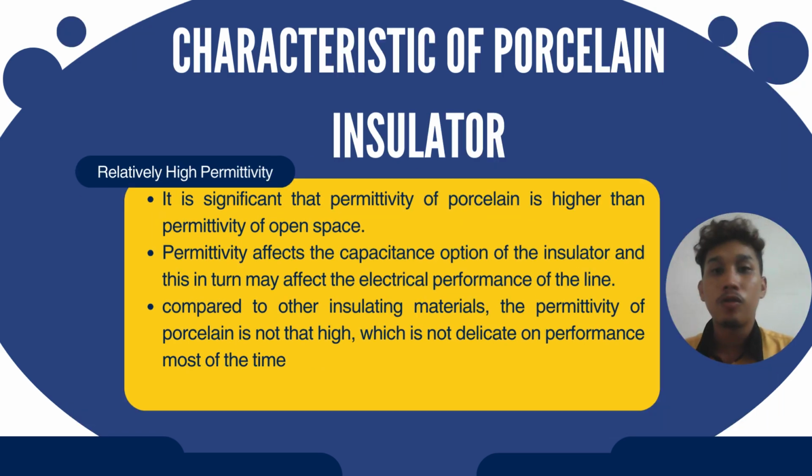We go to the next characteristic, which is relatively high permittivity. It is significant that the permittivity of porcelain is higher than the permittivity of open space. Permittivity affects the capacitance of the insulator, and this in turn may affect the electrical performance of the line. Compared to other insulating materials, the permittivity of porcelain is not that high, which is not detrimental to performance most of the time.